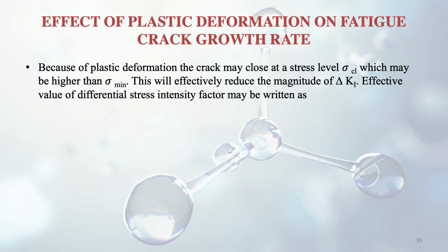Now the effect of plastic deformation on fatigue crack growth rate. We will discuss this now: how this plastic deformation will affect our crack growth rate in case of fatigue. Because of plastic deformation, the crack may close at a stress which is known as sigma CL, which may be higher than this sigma minimum, and this will effectively reduce the magnitude of delta Ki. All these things we have discussed in the previous session. Delta Ki is the stress intensity factor we discussed, so we are discussing it again here.